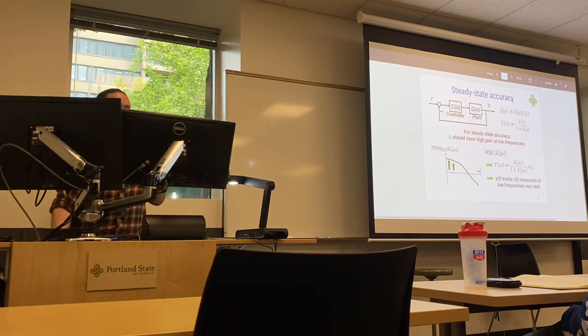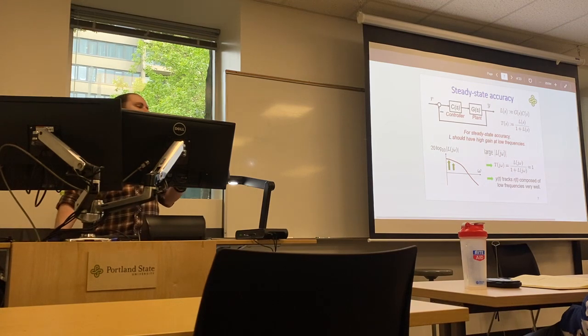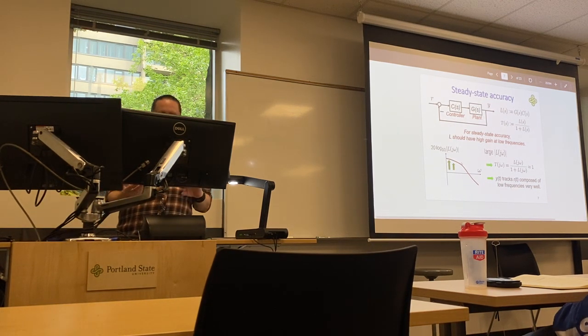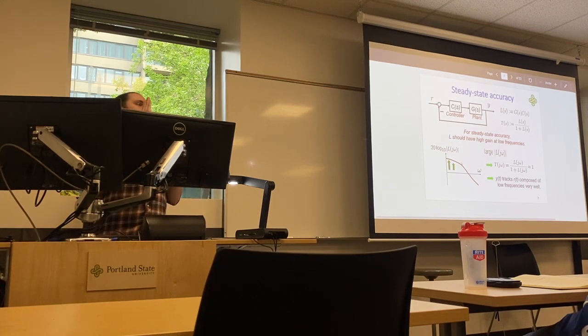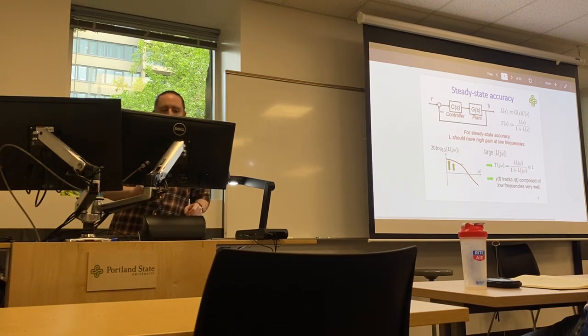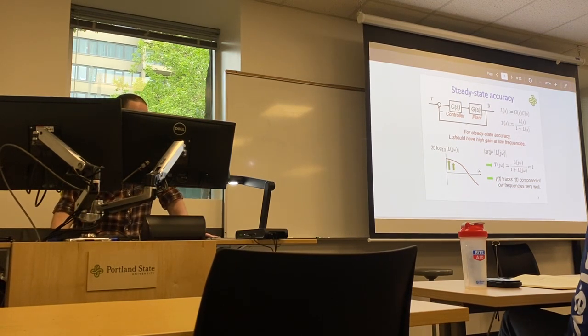So for steady state accuracy, we want the gain to be high for those lower frequencies. If we look back at the lead compensator with the integrator, adding that integrator actually increased our low frequency gain, which helps with that steady state accuracy.